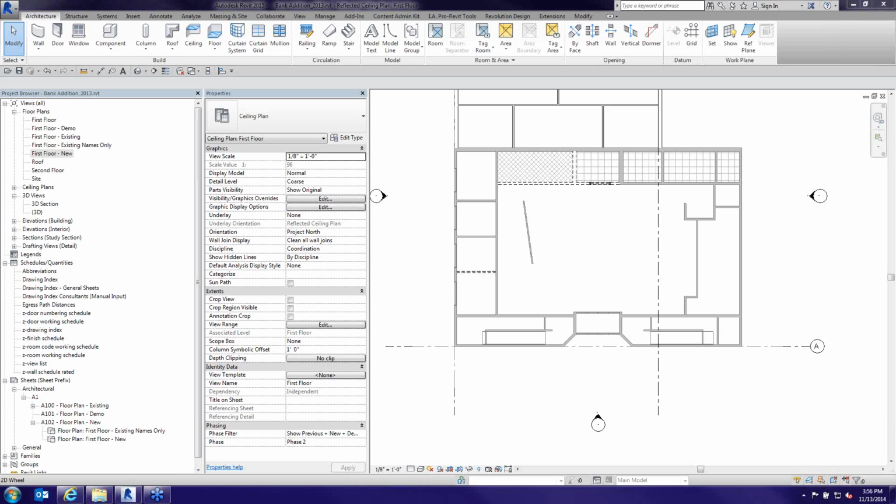So before we even started phasing for remodel, there was 8 phases for existing buildings. So it kind of sounds crazy, but that's in our mind how it ended up working. So for me, if I'm dealing with phasing, I just keep dealing with phasing. But yes, once you throw design options in, it really becomes confusing in what you're dealing with there.